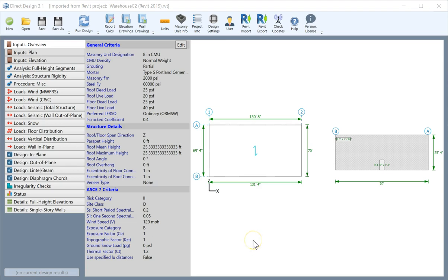And you may have had to massage that slightly coming in from a Revit model, for example, where let's say the parapet was stepped, it wasn't the same height in all places, and you decided you're comfortable with that because for the purposes of structural design, we can just take the tallest parapet height everywhere, something like that.